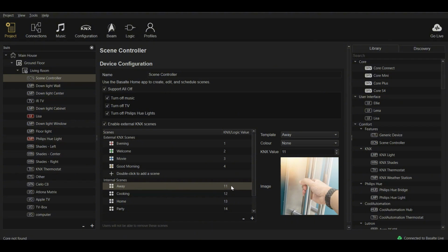So the way I'm going to show it to you, a very popular option is that you can set up a KNX network and have the switches connected to the scene group address, and you already know your scene group address through the scene management, which we're going to show you a bit later. And then you can trigger your scenes. So this allows you to develop the scenes, connect them to a button, and then later on the customer can change what happens in those scenes, and then going forward they can change them as much as they want.